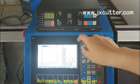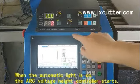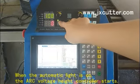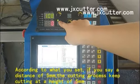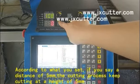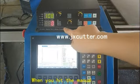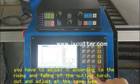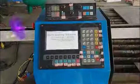Automatic manual button. When the automatic light is on, the arc voltage height controller starts. According to what you set, if you set a distance of 5 mm, the cutting process keeps cutting at a height of 5 mm. When you hit the manual, you have to adjust it according to the rising and falling of the cutting torch.